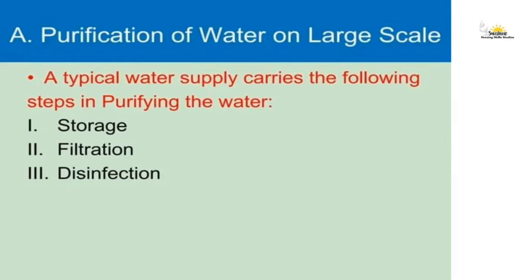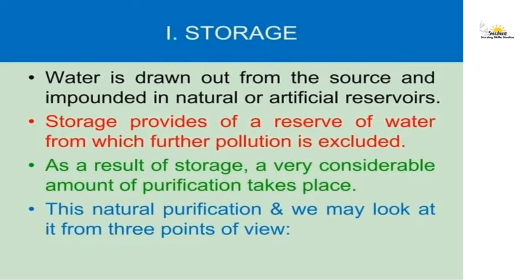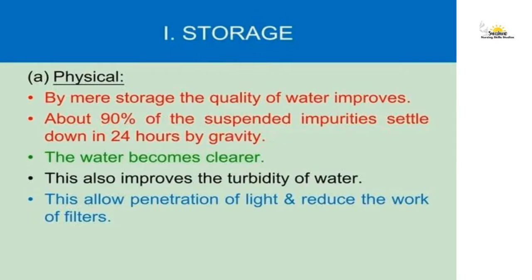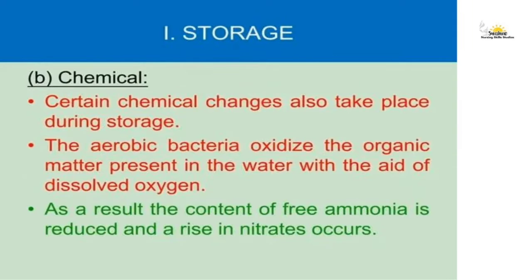What is this storage all about? This storage is nothing but where the water is drawn from the river etc. and kept in one place, and when it is kept in one place, the process of purification starts by physical method. In this physical method the quality of water will improve as all the impurities get settled down within 24 hours by gravity, and the water becomes clearer and the turbidity improves.